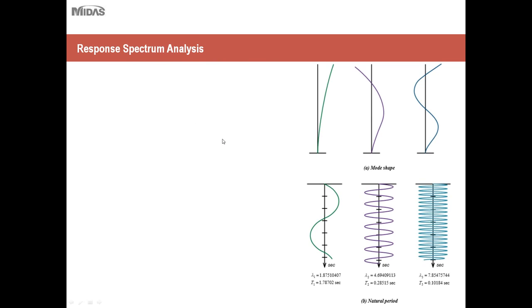All right, so first let's discuss response spectrum analysis very quickly. Response spectrum analysis is required by many building codes, and it's used for everything except very simple or very complex structures. Very simple structures would include one-story buildings or very small warehouses. Those typically use a very simplified seismic analysis method. Complex structures include very large warehouses, high-rise buildings, and very large-scale projects. Response spectrum analysis is the most widely used form of seismic analysis because it hits that middle ground. It's the most conventional analysis type used.